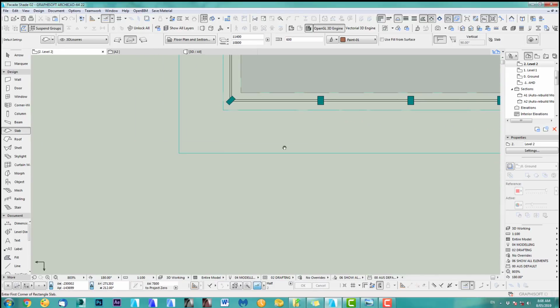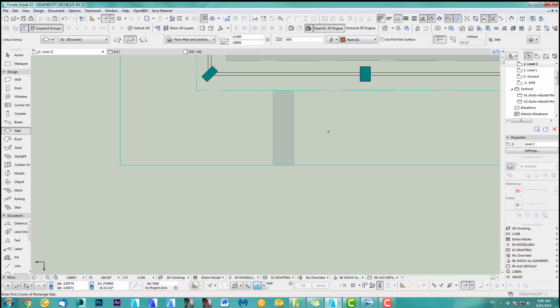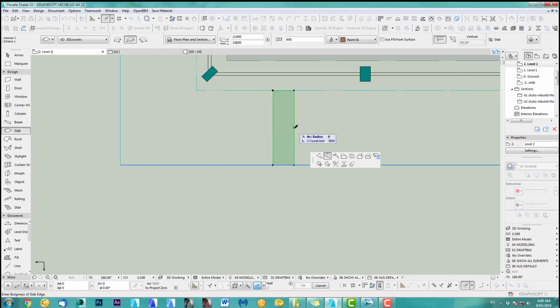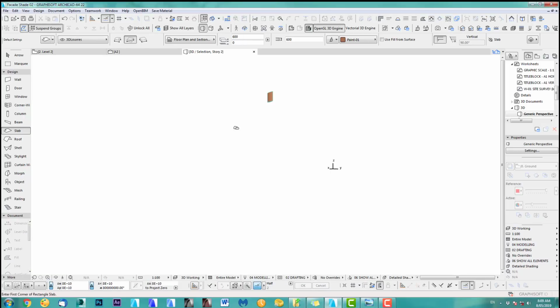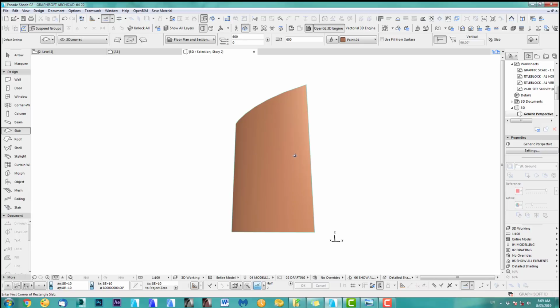Slab. I started my first blade. All you have to do is you go now like this, and obviously, that's the thickness, the width of the blade. So it's 500, and what you do is we just do by eye again, roughly like this. So let's put in 800, and same on this side, 800, and all you have to do is move this back here. And we got our first blade.